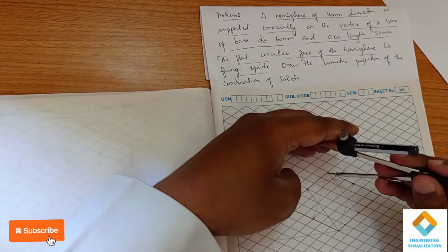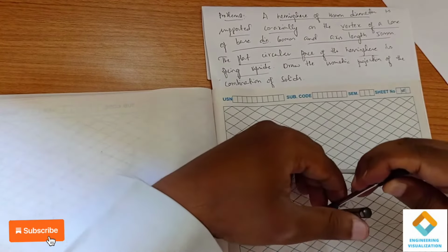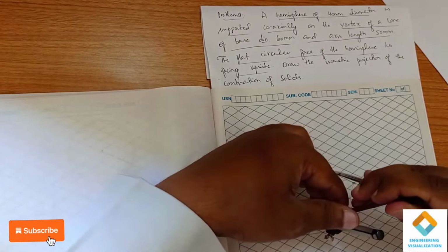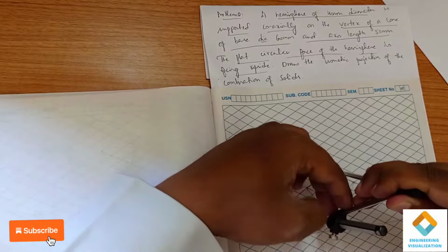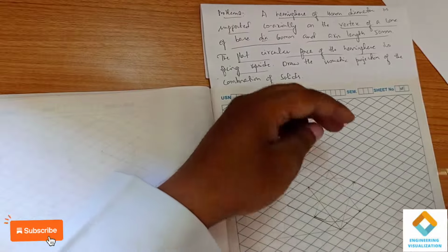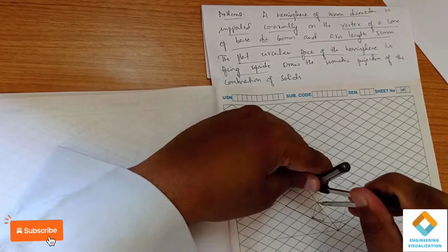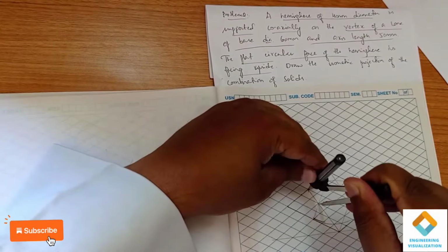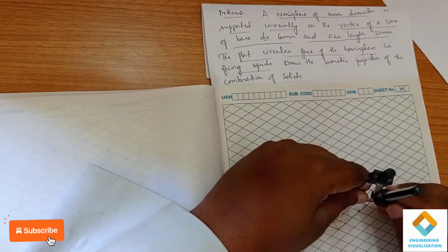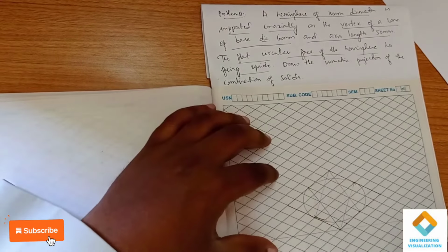Again from this point, measuring this length, like this. Then the third point, we have to measure from this point using the compass. Third arc, next fourth. Measuring again this distance. Okay, so we have constructed an ellipse.